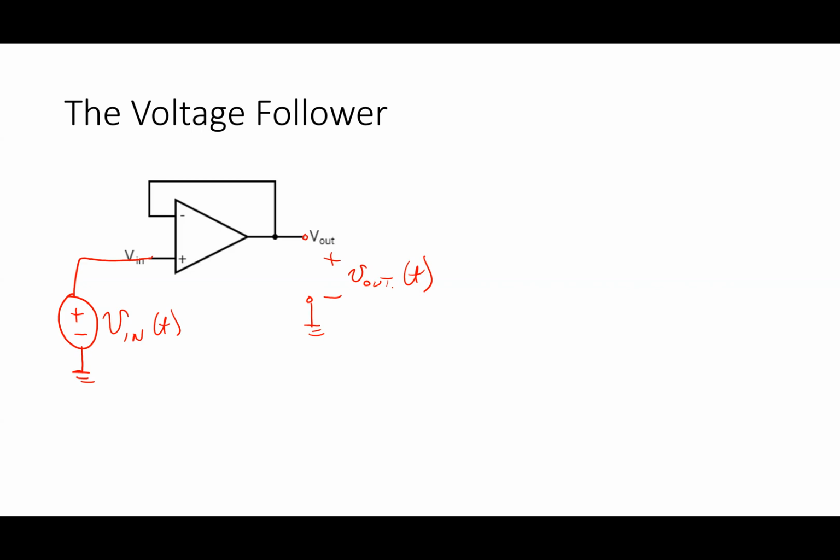Where do I start with any of these problems? Finding voltages. Okay, so what do we know? We start with our golden rules anytime I have one of these. So what are my rules? Well, I have I plus here and I minus here. What do I know about those two things? They're equal to 0. I plus equals I minus equals 0.